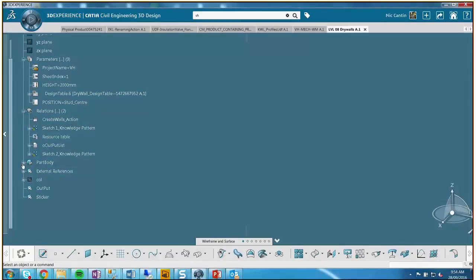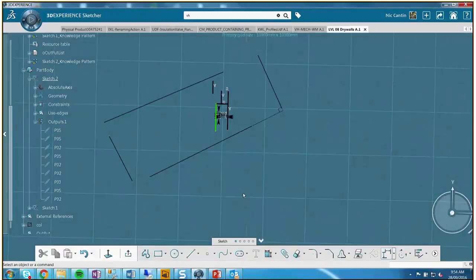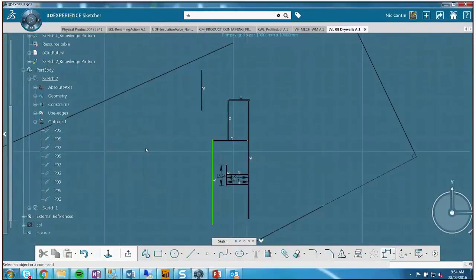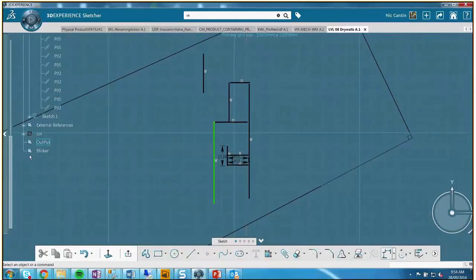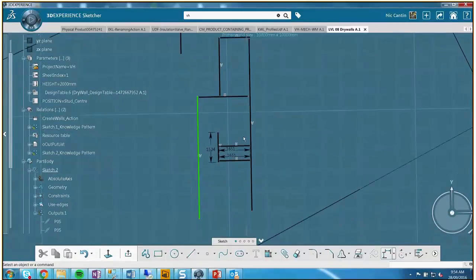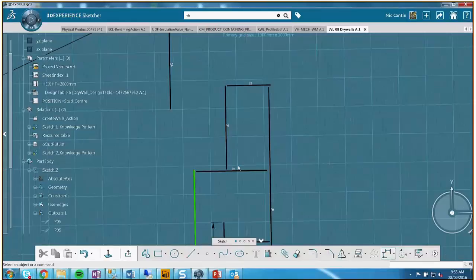And then what we do is we take a sketch. I didn't do the whole floor, but I just did a few outputs. And you output each of these lines and name them accordingly. In our case, we're not designing all of the stud walls, so we actually take a sticker overlay, and we just trace out all of the wall lines, and then we can constrain them according to the dimensions that the architect provides us.